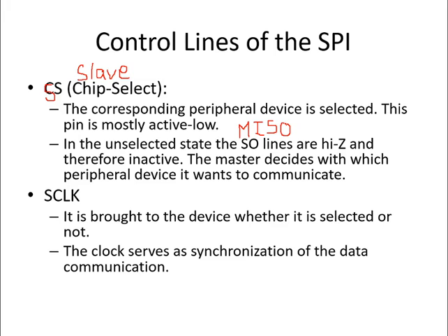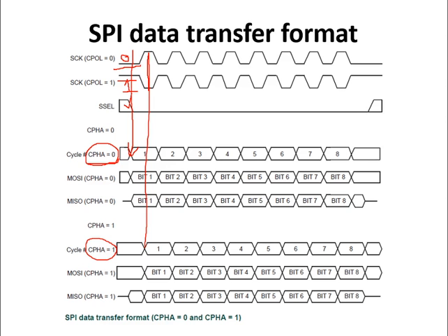Then the other one is SCK. SCK is nothing but the clock signal. It is brought to the device whether it is selected or not. The clock serves as synchronization of the data communication. You can see that with respect to SCK, your data bits are given there.